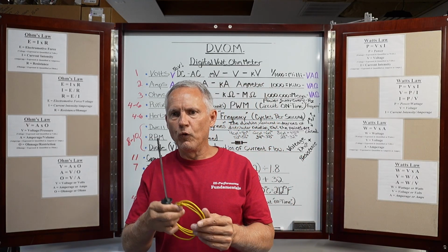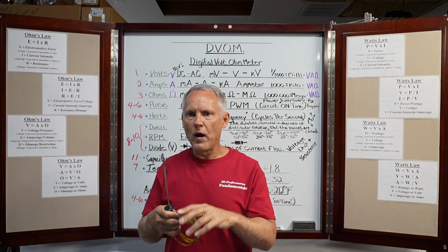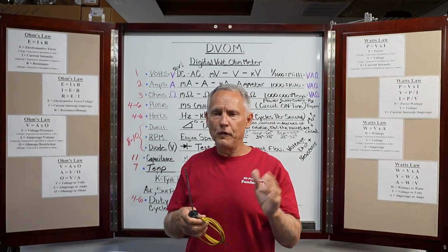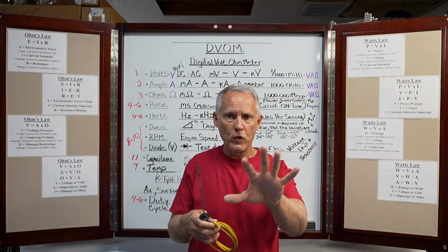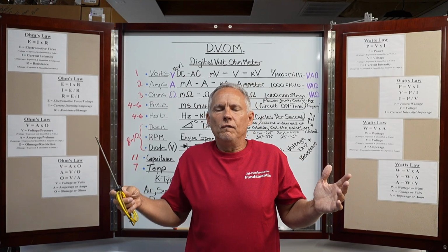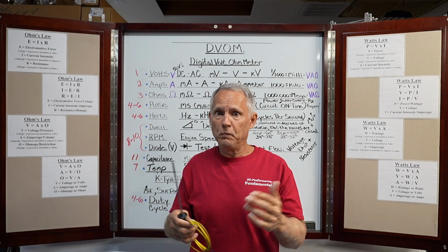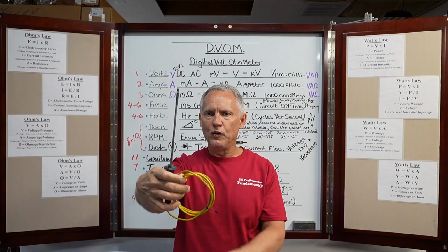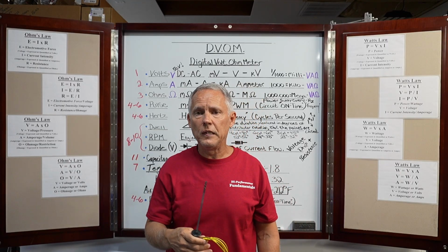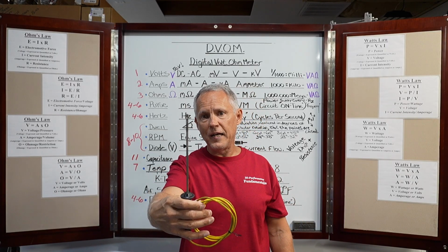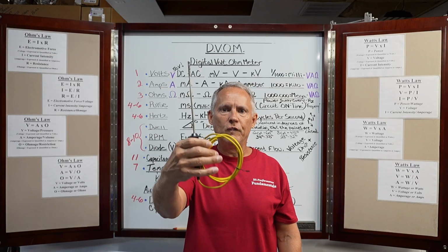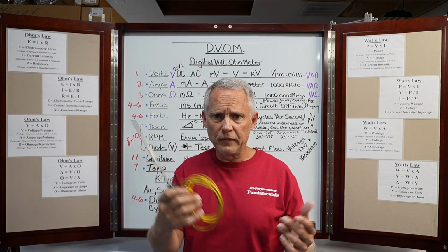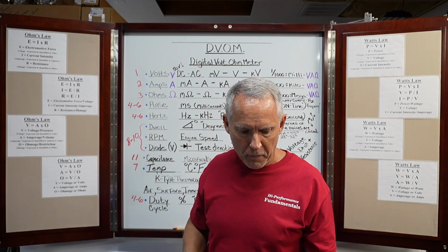Now, things like this can come in real handy if you're doing diagnostic work, and it's getting a little off track. Let's say, for example, you're looking at a value of an interior temperature sensor. You know where it's located, once you've found it. It says it's 147 degrees in here, which, believe it or not, depending on parts of this country, you can get that hot in there. You lay this in there next to it, plug it into your meter, it should say something close to 147. If that reads 147 and this reads 92, something's wrong. Now you have determined that you have a problem with that sensor. This is how you're going to diagnose it. Just an example. You can use it for many other things besides that. But those are really handy.